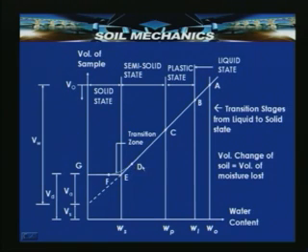One of the possible reasons for this phenomenon is that air starts entering from this point. This is the point where air entry starts, and by this point mostly the water is replaced by air, and the soil grains are pressed so close that there will not be further reduction in the volume.